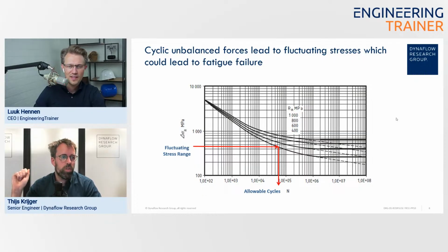Probably also good to know for people looking at these kind of systems: if you're analyzing a system that's in use, and they have observed vibrations, it's something to be cautious about, that if the vibration levels are problematic, you expect failure within a short time frame.